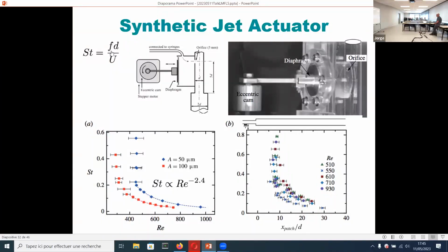Yeah. So how can you put noise in water? But the acoustic actuator then. Yeah, because what happens on boundary layers is that the turbulence is usually triggered by the disturbances that come from upstream, and basically what comes from upstream can be to some extent viewed as noise, because you have all kinds of things that arrive on the boundary layer.